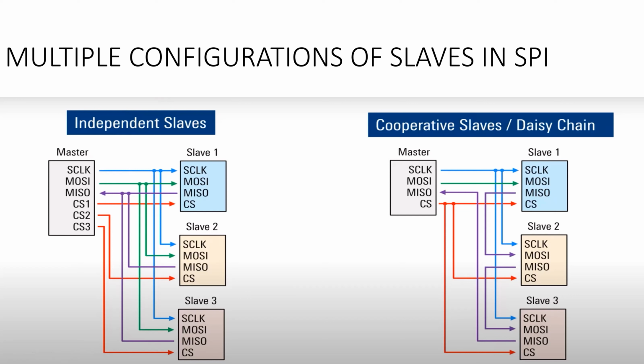This chip select 2 line is there, right? It will be pulled down, and the serial clock was already there. With these two combinations, we have a 0 1 combination. The chip select 2 will go low, meaning it is at 0, and the clock is at high.